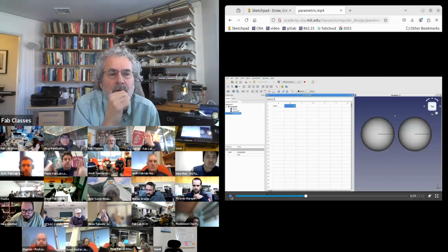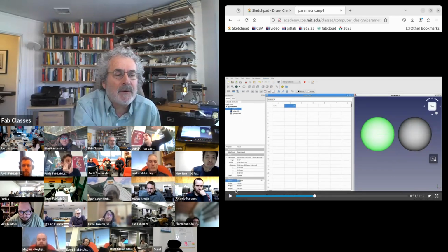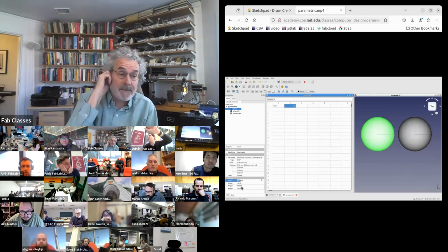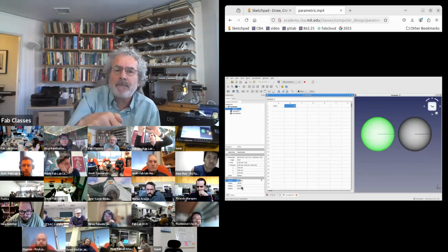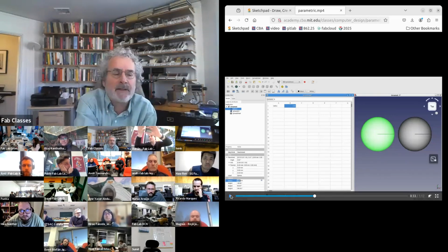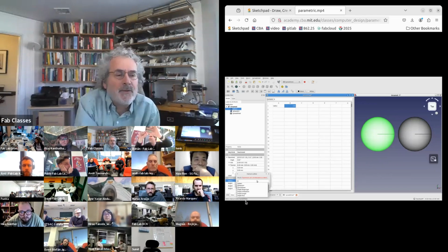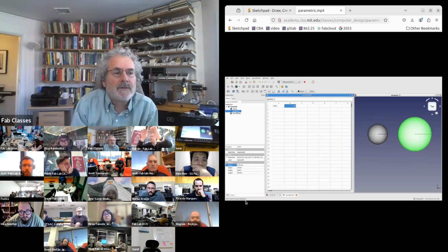Here I'm going to rearrange my windows. Now, remember down here, each object has data. I can go into the data, and instead of typing a number, I can put in a variable from the spreadsheet or a math formula. So here I'm going to tell it, use a formula, use the spreadsheet, and take my variable. And I'll do that for both of those spheres.